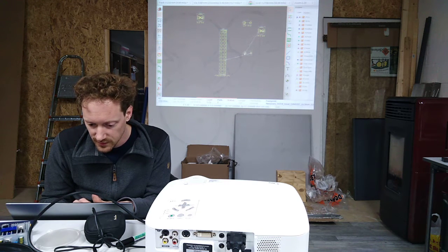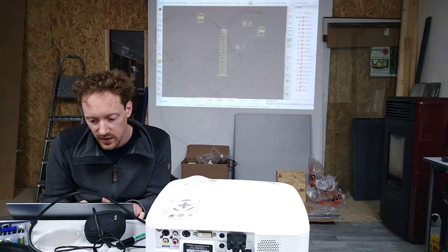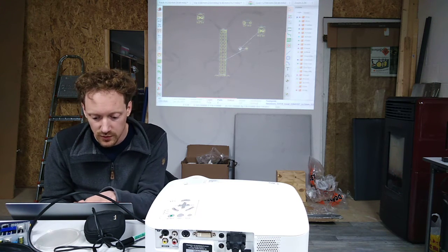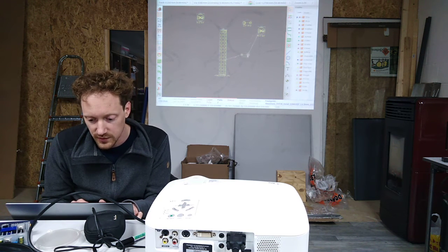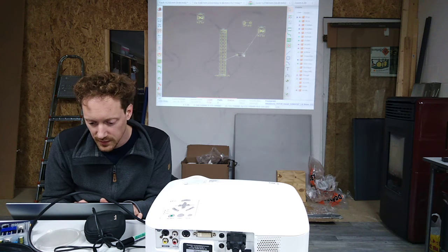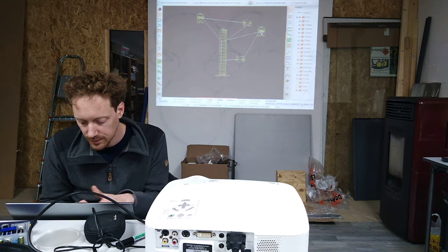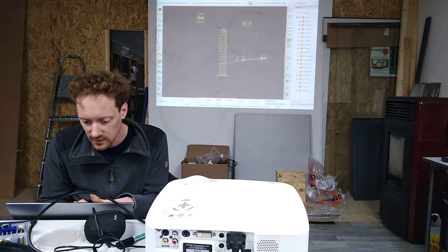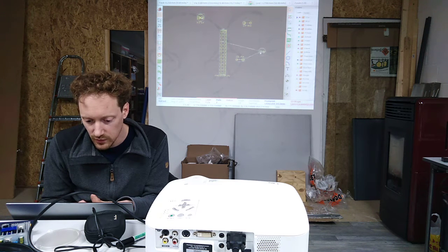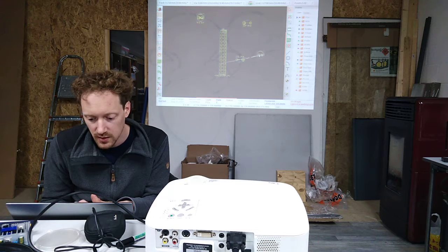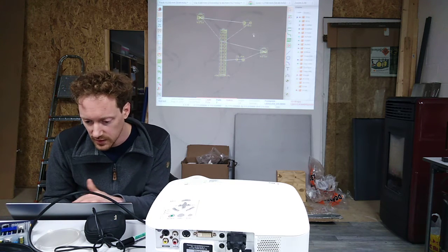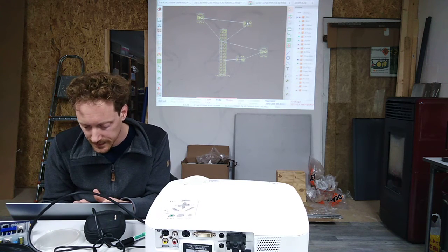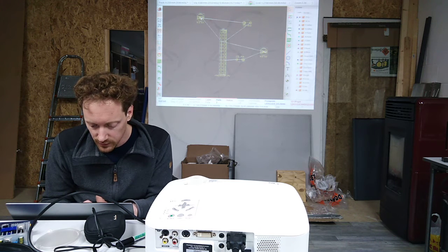And this is then probably the resistor. It has to be attached to pin 19. So 15, 16, 17, 18, 19, indeed. So we rotate it because that is easier. So let's place this LED here. The resistor here, place the LED here, and it has to connect to either this one or this pin, which will be ground. So we'll just put it here, then we have this other LED that should be connected to that one.